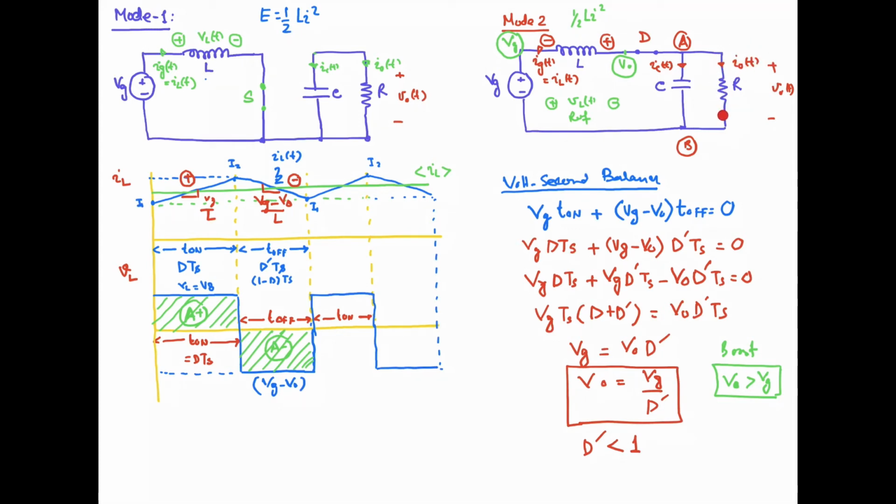There will be the average current through this load resistance, and the high frequency current will pass through this capacitor, because for high frequency the capacitor offers very low reactance. So the high frequency component, that is the variation delta I or 2 delta I over here, at the switching frequency, will pass through the capacitor, and the average current will pass through your load. So your supply is contributing towards the load current in the second mode of operation.